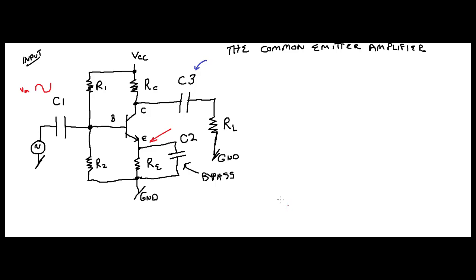That means then this capacitor down here, I have to find where my pen is. There we go. This capacitor right here, C2, right, is going to be seen as a short. That short is going to bypass this resistor RE. Got it? So if this shorts this, it's like this resistor isn't even there for the AC signal. Hence, you can see now that the emitter basically is tied directly to ground for that signal.